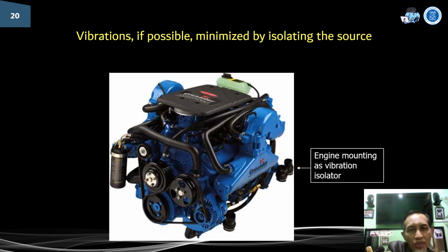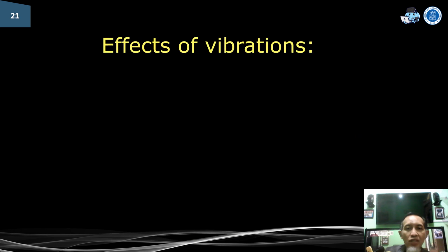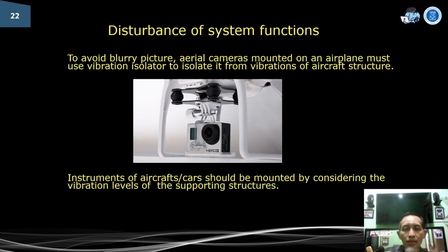Vibration, if possible, is minimized by isolating the source. For example, engine mounting acts as a vibration isolator. There are many effects of vibration. First, disturbance of system functions.